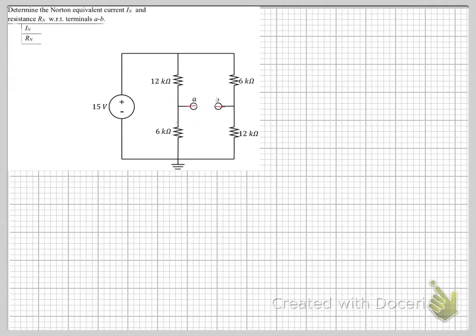Okay. So, lucky enough, there's no dependent source. So finding our Thevenin resistance is going to be pretty simple. We first start by switching off the sources. Remember how your voltage source becomes a short. So this is now a short. So now you must find the resistance between those two nodes. So let us draw this circuit and try to determine this equivalent resistance.